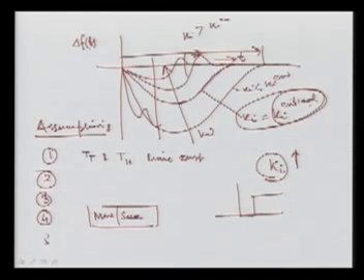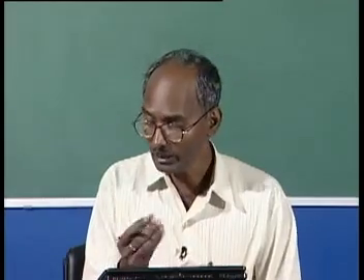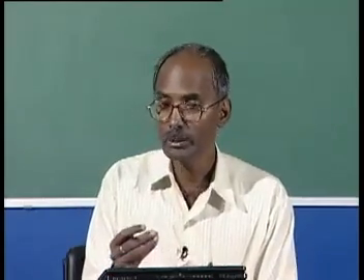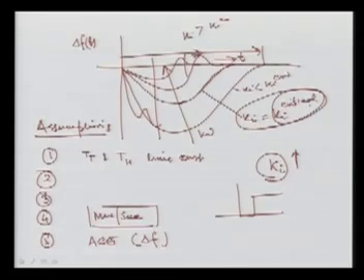Fifth assumption that we made, that is also very important. We have assumed that ACE is available as a continuous signal. This area control error, ACE, is nothing but your change in frequency. We have assumed that it is a continuous signal that we are getting, but it is not so, because we are using some measurement circuits, and those measurement circuits basically depend upon sample data acquisition, meaning we are measuring at certain intervals of time.